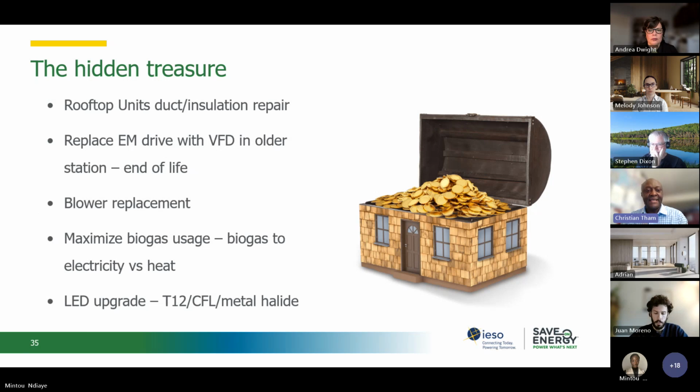So where did we find the savings? Stephen said it so well: a jockey blower. It's a great way. But instead, you keep the jockey blowers, a smaller option, and the existing blowers are still there, and you maximize savings instead of working on a bigger existing blower and bringing in VFDs. The cost implications will be huge. A jockey blower replacement could be one area to look at. So that was one of the savings that we found there.